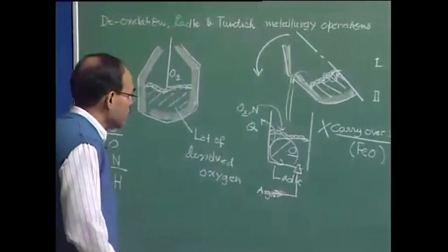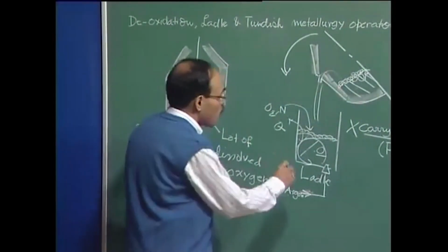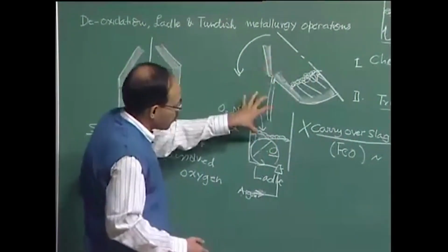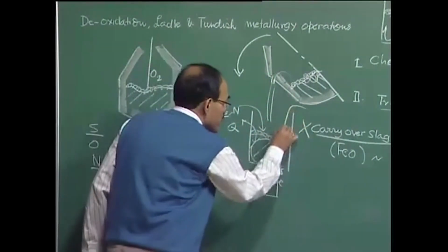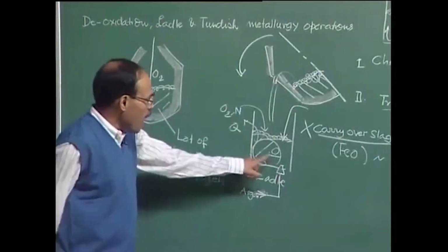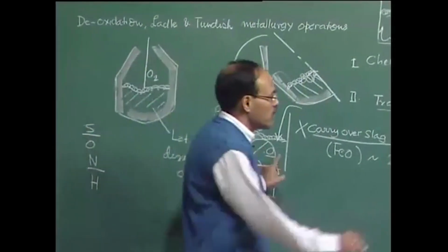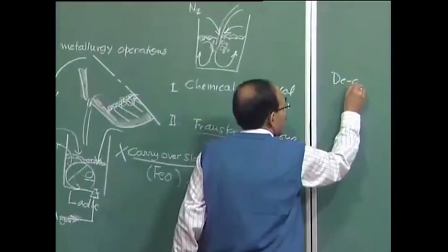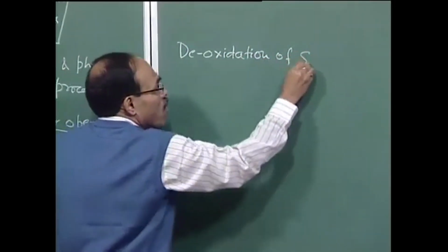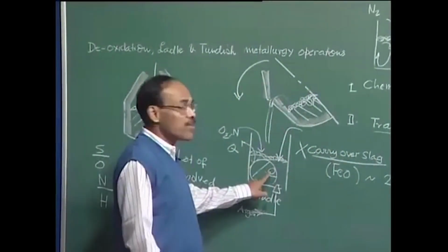We can see that before the material is completely filled, as the basic oxygen furnace is being emptied, we are going to continuously add deoxidizer elements into the steel bath. Now the first step, as I mentioned, is to drive out this oxygen, and this is called deoxidation of the steel bath. And to deoxidize the steel bath, we basically add elements which have very high affinity for oxygen.